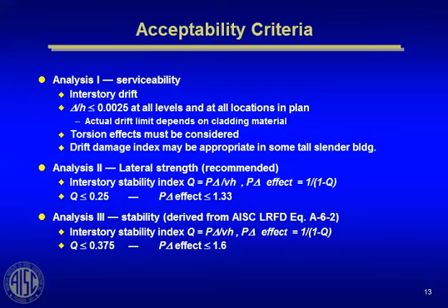And then the new direct analysis method also is basically based on the notional load concept, which you're going to be hearing a lot about in the next couple of years as seminars start being developed for Appendix 7 and Chapter C in the 2005 specs. So I'm not going to go into that anymore, but what I did want to say here is that the concrete code does have a limit on this Q value, and it actually requires you to check under sustained gravity loads.